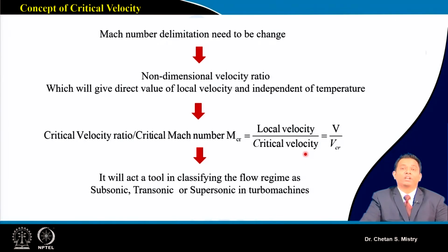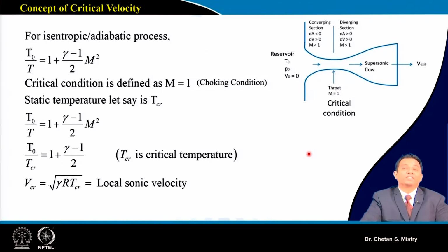Now you might have studied in your fundamentals of aerodynamics or in gas dynamics or advanced gas dynamics. There also we have discussed this critical Mach number. Now we will see what exactly is the use of this critical Mach number. If we use this kind of velocity ratio, then we are able to understand whether the flow in my turbo machines is subsonic, transonic or supersonic. That is very important. So let's see how we understand that part.